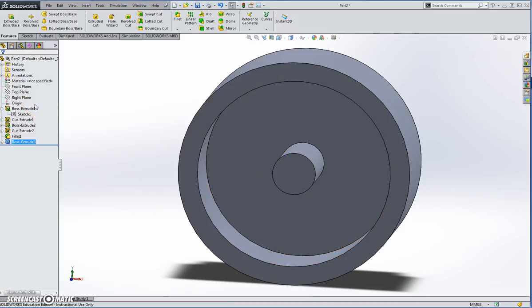The last thing I need to do, and I'm running short on my time here, is to sketch some, I guess, kind of spokes, if you will, on the inside of the rim. You'll see that in the model. What I'm going to do there is to create what's called a pattern, and then I'll create a feature and then use the pattern operation to actually create multiple versions of the same thing.